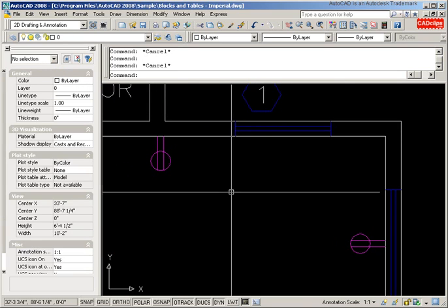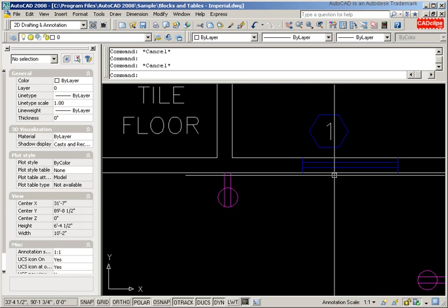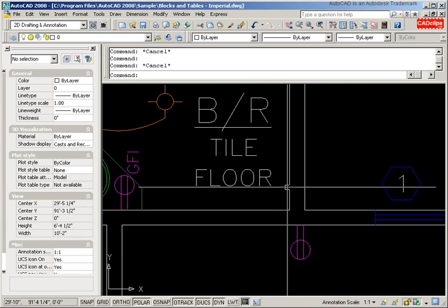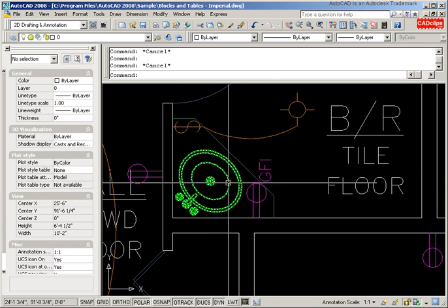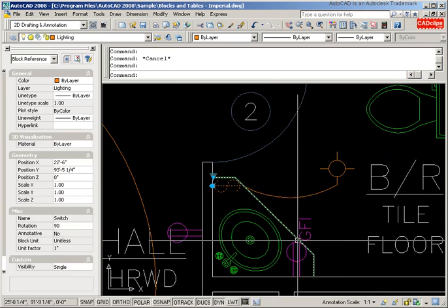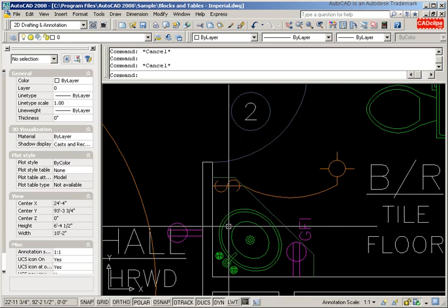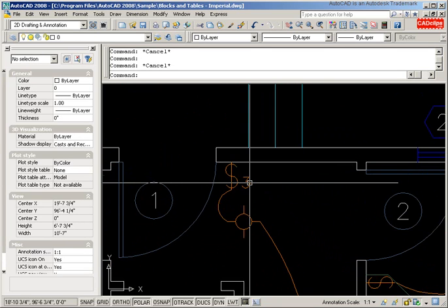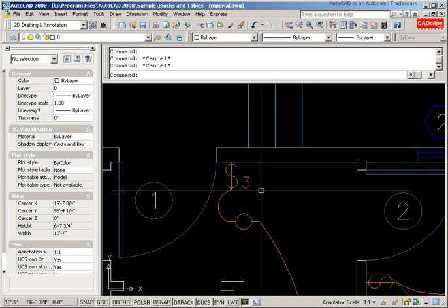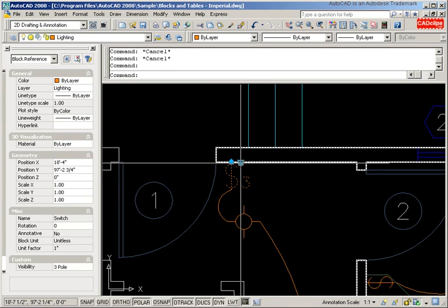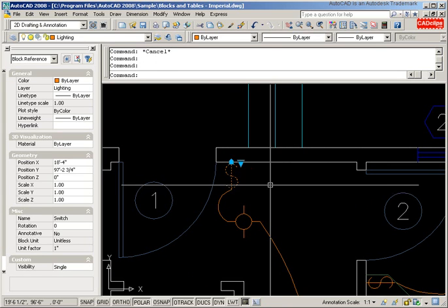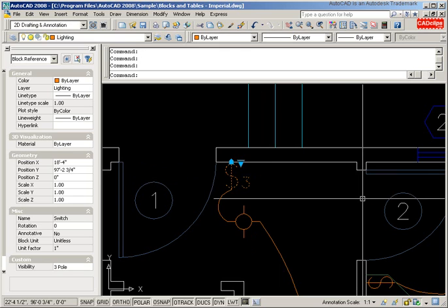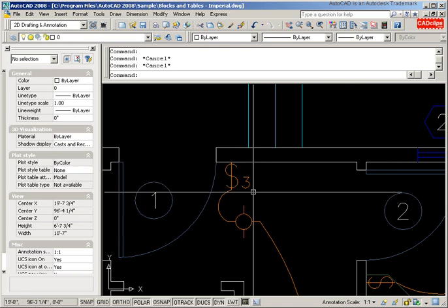and the name is window. So this is a sample of blocks: here's a window block, here's a sink block, here's a light switch block, here's an overhead light block, here's an outlet or receptacle block. Okay, there's a 3-pole switch block, a little bit different. These are dynamic blocks. You can click on here and make it a single pole or a 3-pole. So that's a dynamic block.